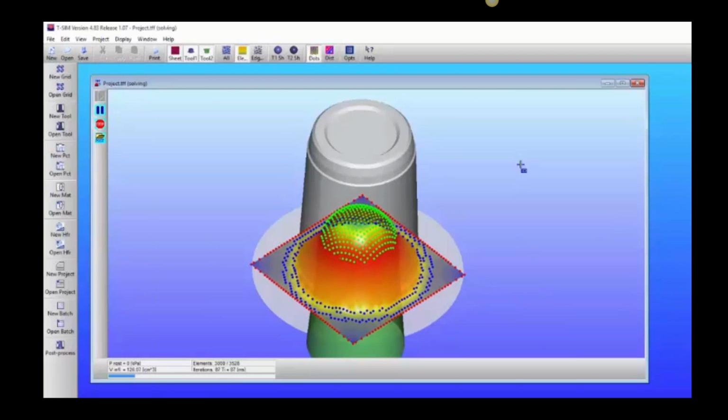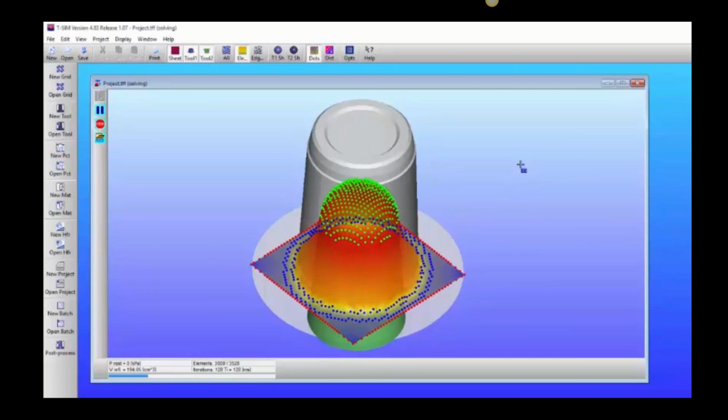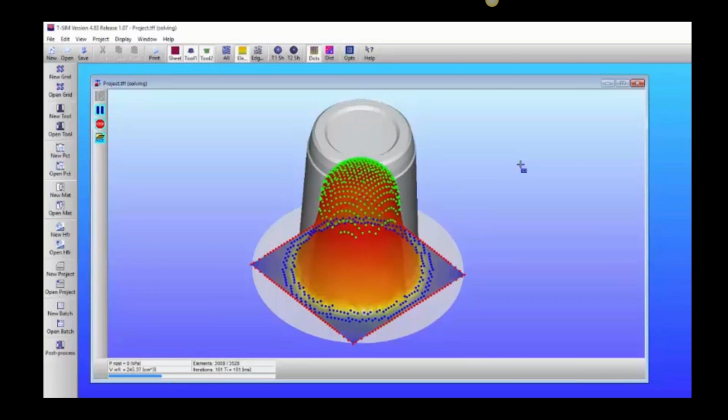And as we define this, the plug will move 111 millimeters, at which point the vacuum will come on and pull the material off the plug and up against the tool surface. Now you'll see at the bottom left here that that happens after the 200 milliseconds that was specified in the process control.